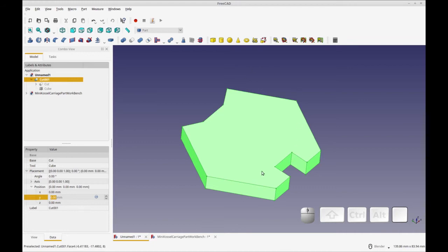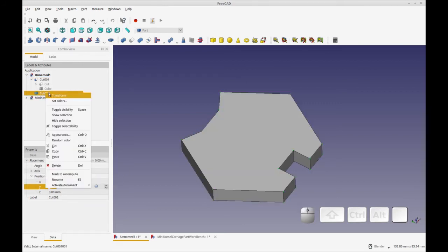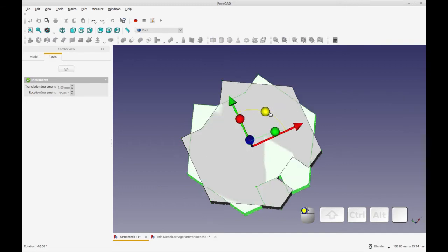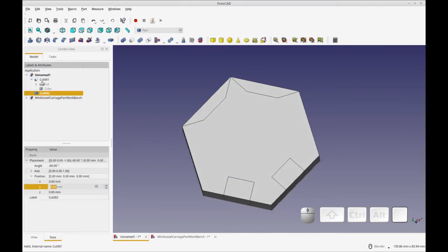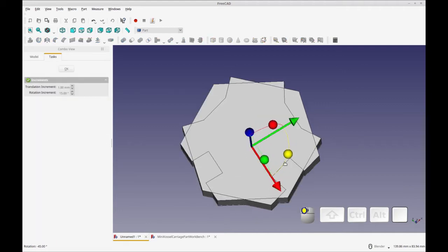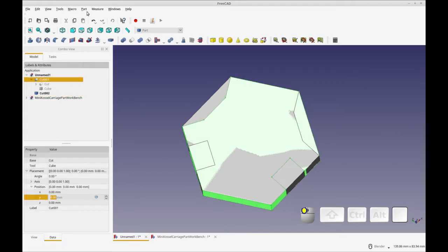So to create an array of these around, the polar array could work, but what we're going to do is a simple copy. First we're going to create a simple copy, then we're going to highlight it and do a transform, because in this case the degrees end up being right dead on, because we're working with 30-degree objects here. Oops, went one too far. Let's go back. Or one too short. We want it there.